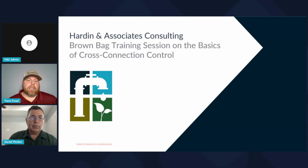Turned out to be not much at all, just a washout area they use to get leaves and things off the roof. But access has generally been my biggest hurdle as it comes to CSIs. To mitigate those problems, you really just want to communicate with your customers as the water purveyor to let them know, hey, this customer service inspection is coming, and they do have to have access everywhere you use water.